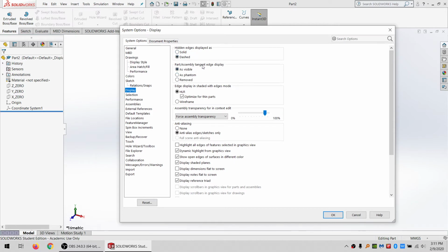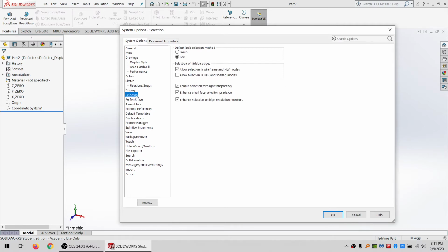This is actually kind of neat when you're working inside of a part that's inside of an assembly. The rest of the assembly can be made to be kind of invisible, and it just makes it a little bit easier to work on that particular part without having to hide other things. And I'm going to drop that down just a little bit, make the rest of it a little bit more invisible. It's still visible. It's like it's made out of glass or something.